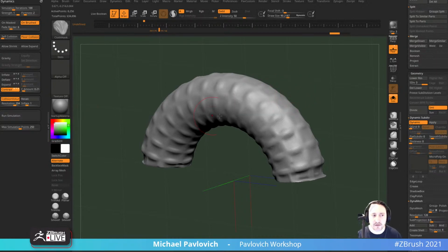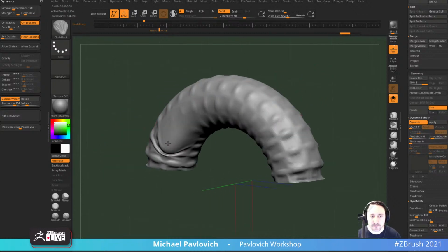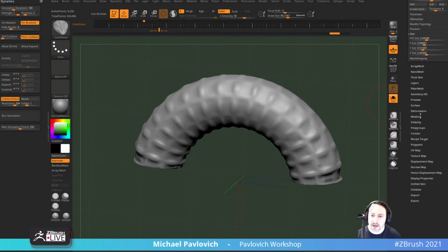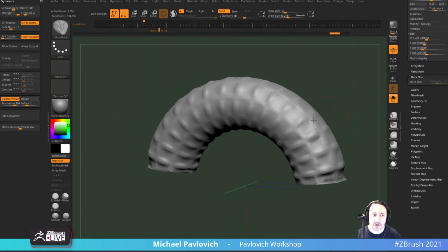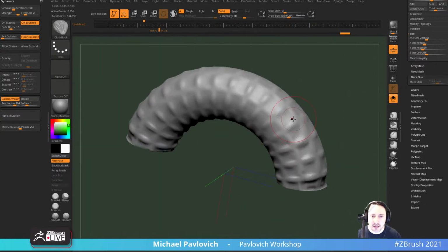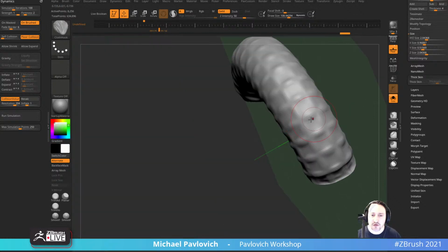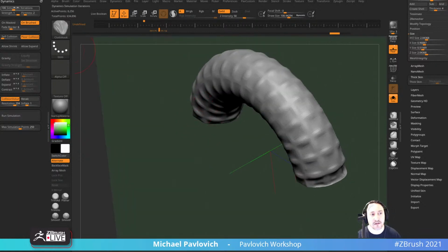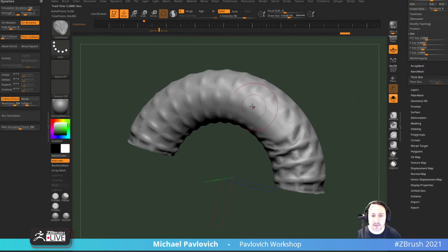However, you may want to go ahead and turn that off while we're using our brushes, while we're going through here and just pulling the stuff around, just so it's not constantly contracting as you're doing this part here. There's another area too where you can go down here and you can limit the effect. Now we do have a collision volume in here, so it's brushing up. You can see it's not going to go into that mesh, or at least it shouldn't. If you go too fast it will, because it's just math, and if you don't have your simulation iterations turned up, that's another thing you can do. Turn that up, and now when you do that, it'll run a lot of iterations, so it's going to make sure that it's maintaining.